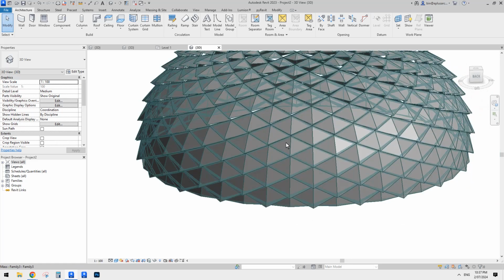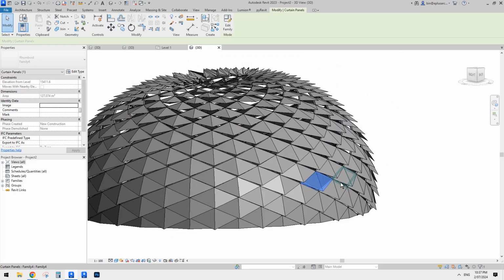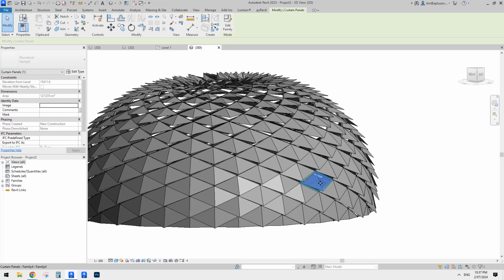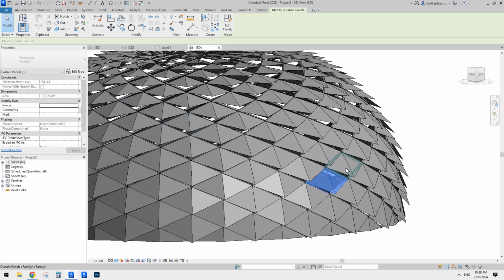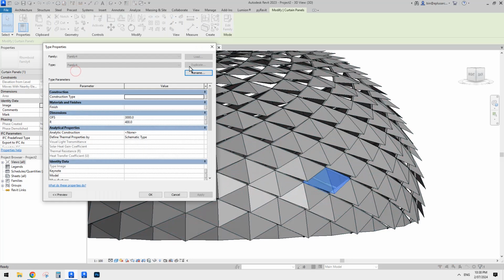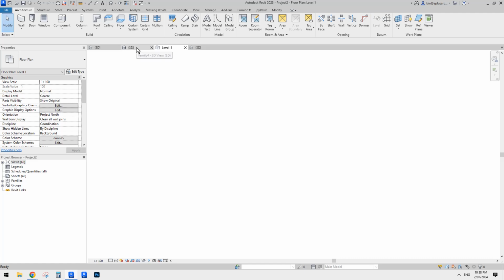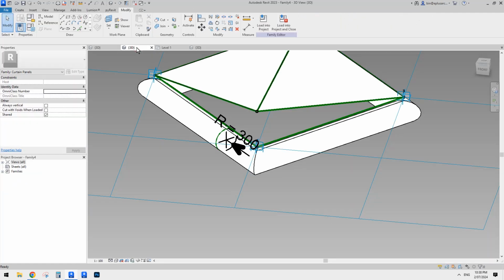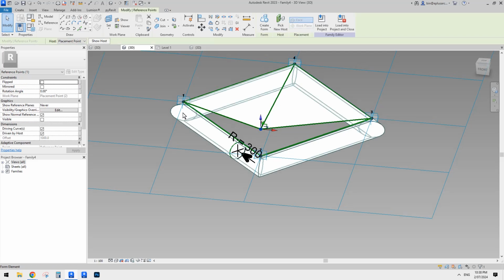Also, in case you want to open only some of them, with a different angle, actually I'm not quite sure. So let's see if we can. We can't really duplicate. So I think the only option for us then is to make this an instance parameter instead of a type parameter. So let me just quickly have a try.